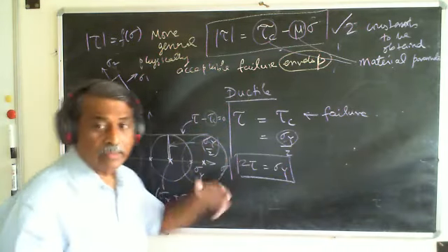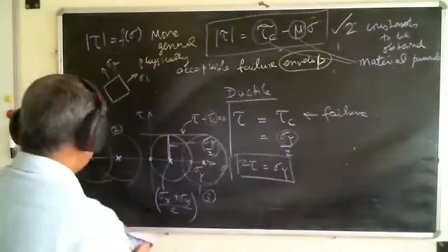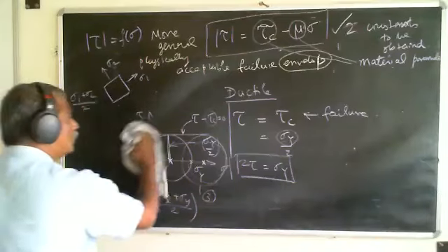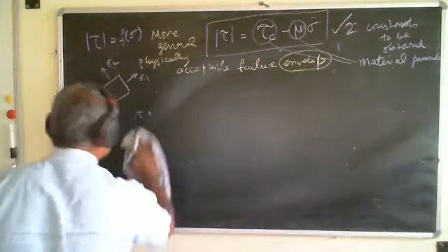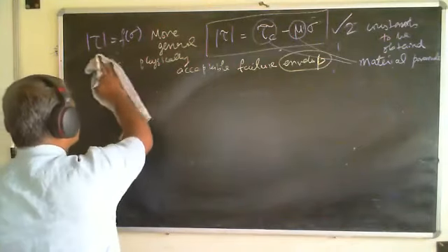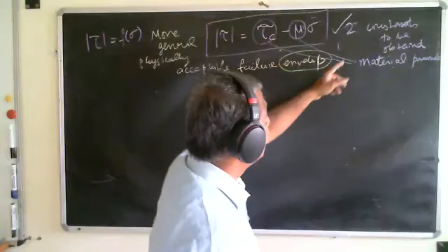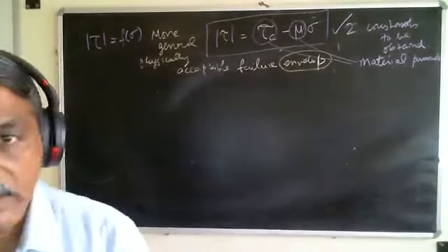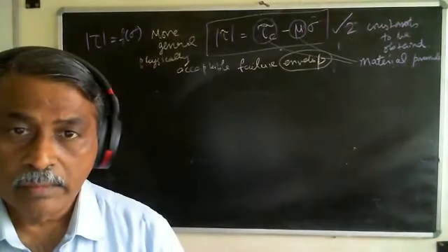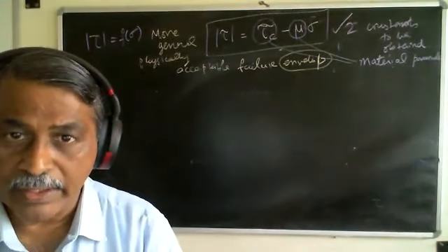For the ductile material, it remains the same. All right. So we did it for ductile material, we did it for brittle material. We can do a similar thing for frictional material also. But the fact of the matter here is I need two constants to be obtained. How do I obtain those two constants? Of course, experiments. But how many tests should I conduct to obtain the two constants?